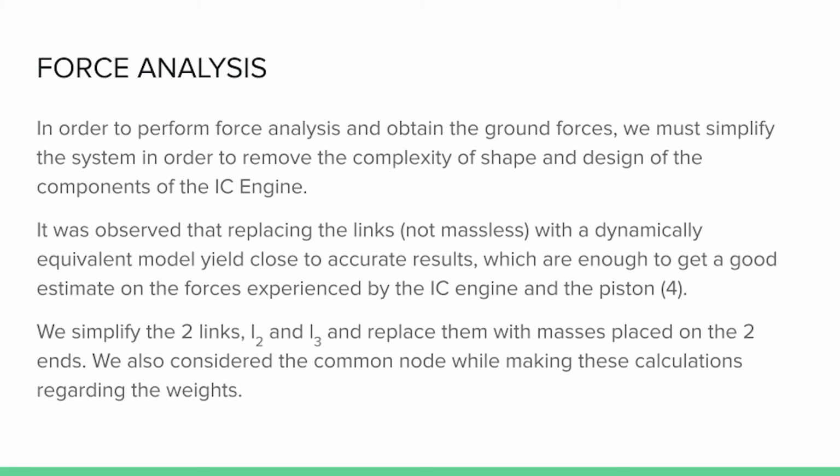So now, moving on to force analysis, in order to remove the complexity of shape and design of components of the IC engine, we must simplify the model, and for that we should perform force analysis. It is observed that we can replace the link with masses with a dynamically equivalent model to get a good estimation on the forces experienced by the IC engine and the piston. We simplified the two links L2 and L3 and replaced them with masses placed on the two ends. We also considered the common node while making these calculations regarding the weights.